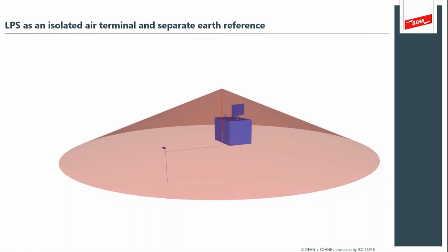And what you get is essentially the ability to build two grounding systems that are separated with enough distance so that if you get a lightning strike, you can safely divert the current away from the structure into the earthing system. So here you have all of the aspects illustrated in one nice shot. You have the air terminal, down conductor, and an isolated type A earthing electrode.